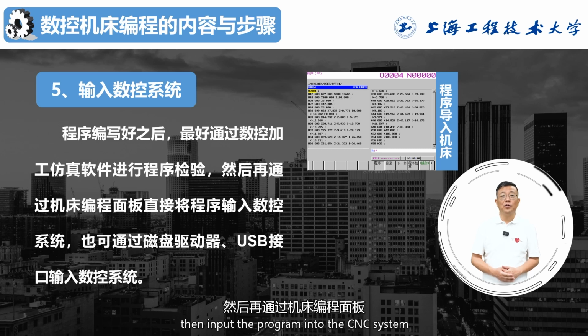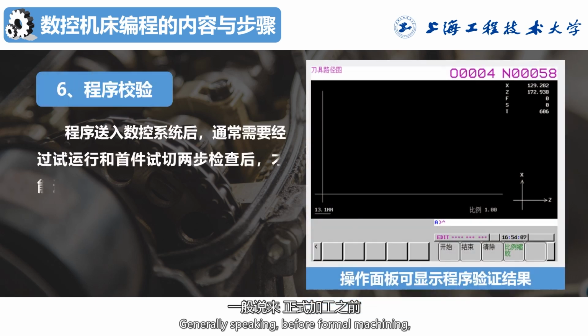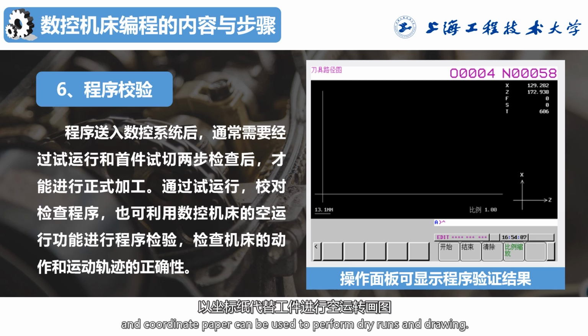Then, input the program into the CNC system directly through the machine tool panel or via a disk drive or USB interface. Generally speaking, before formal machining, the program should be verified. For planar parts, a pen can be used instead of a tool, and coordinate paper can be used to perform dry runs and drawing.